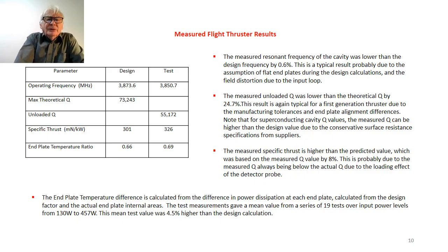When we carefully tuned and tested the cavity, we arrived at a resonant frequency of 3,850.7 megahertz. So this is about 0.6% error. And if you go back to the previous slide, you can see that we did expect an error due to the design calculation assuming flat end plates.